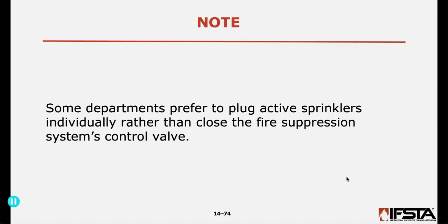You put this in there, get quite a bit of water that comes out, and then you open this mechanism up and it plugs the sprinkler essentially. Some people will do it with wood wedges. They'll hammer two wood wedges together to cover that hole where the water is being discharged. And then you're controlling the water there at the sprinkler head as opposed to shutting down the entire system.